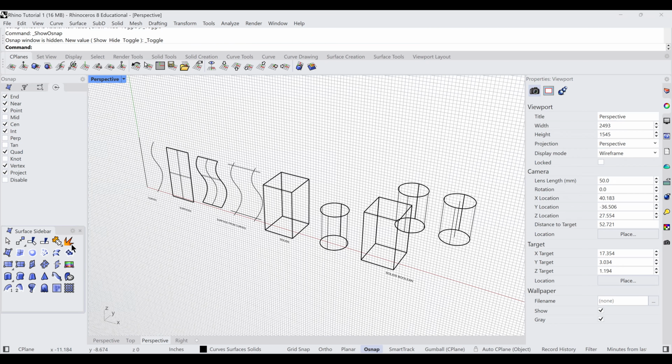You can select tools like we have down here. You can have the move tool and the trim and all that. You can select tools individually by their little icons. You can also use the command area up here where you can actually put the command in. So you can put in the word move, the tool will come up and it'll guide you through the steps to move. It'll say select your object, move, pick the object, move it to where you want to locate it, and you can move copies and things like that.